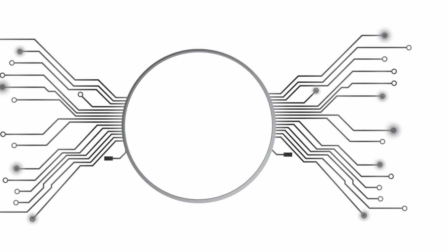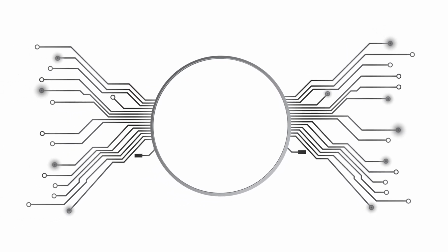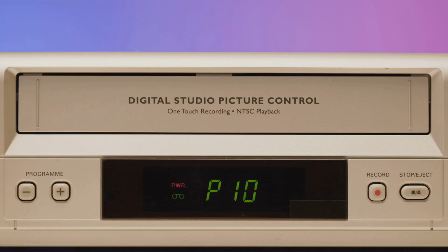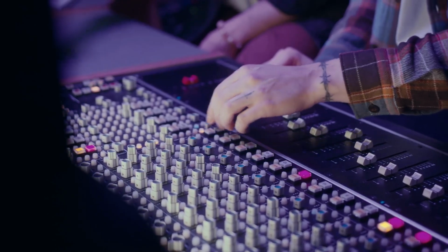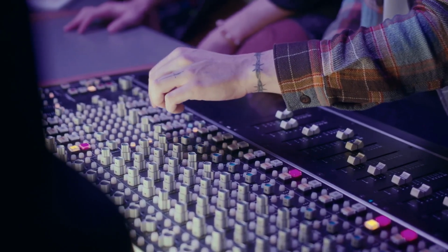While PID control is powerful, several common pitfalls can hinder its effectiveness. Overtuning the PID controller is a common mistake, leading to excessive overshoot, oscillations, and instability. Adjust the gains gradually and observe the system's response carefully.